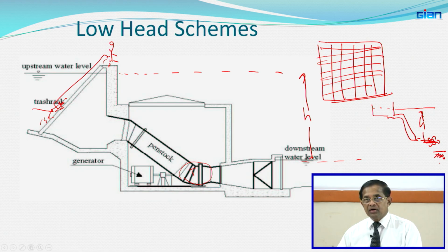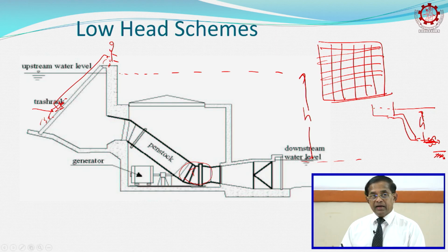That is a high head project using impulse turbines, right. But here in a reaction type turbine, usually I am sure you have heard this word, Francis and Kaplan machines are reaction turbines. So, they are fully immersed in water and the applicable head is the lower reservoir water level and the upper reservoir water level, the difference, that will be the head.